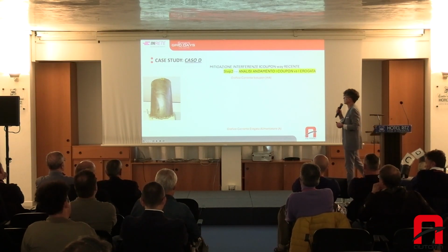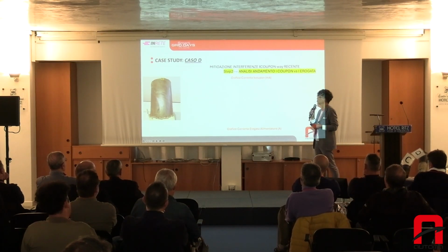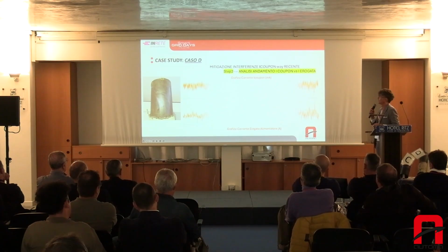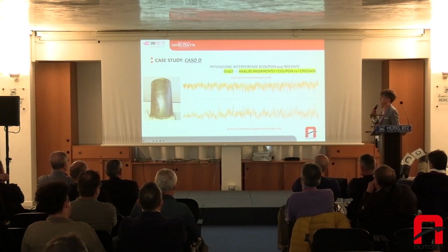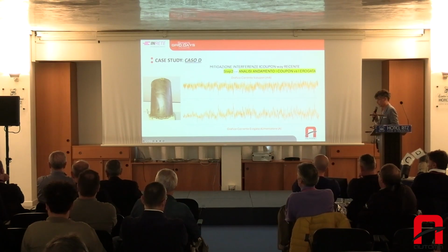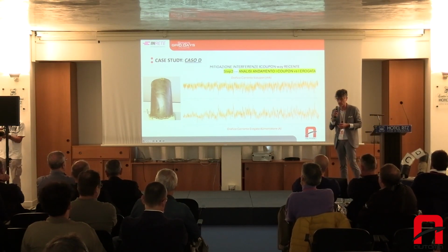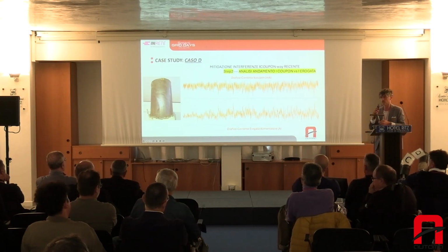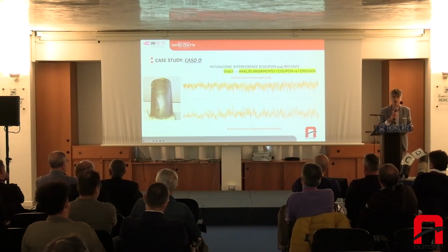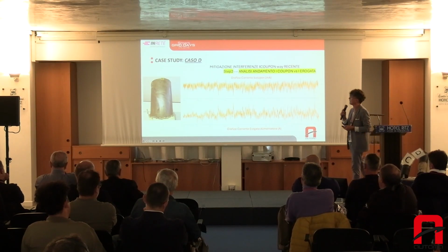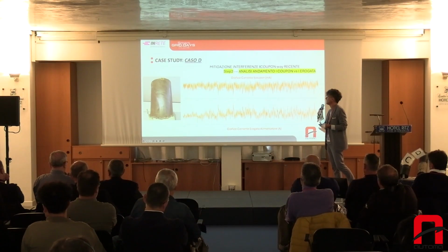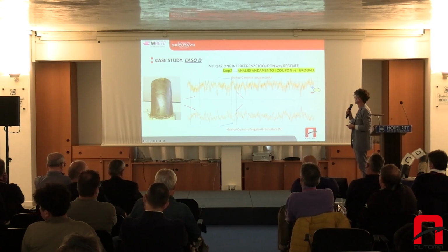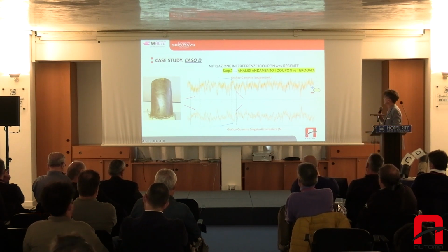As for step 2, I can do something more. I can analyze the coupon current graph, comparing it with the graph of the current provided by the power supply. When we are in an anodic condition, also in this case, we will find the same situation. Let's analyze the graphs.